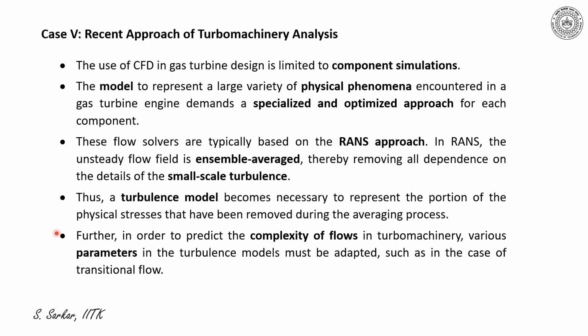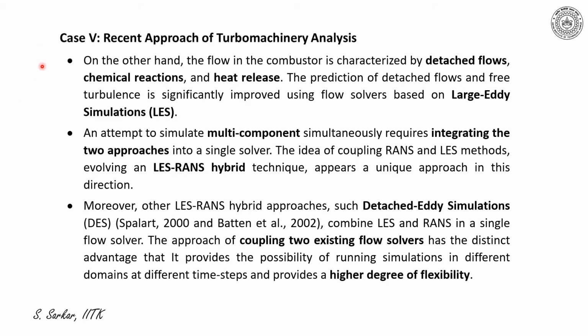I have already indicated that while predicting transitional flow, we incorporate some modification or addition in the turbulence models. On the other hand, the flow in the combustor is characterized by detached flow, chemical reaction, and heat release. The prediction of detached flow and free shear turbulence is significantly improved using a flow solver based on large eddy simulation.